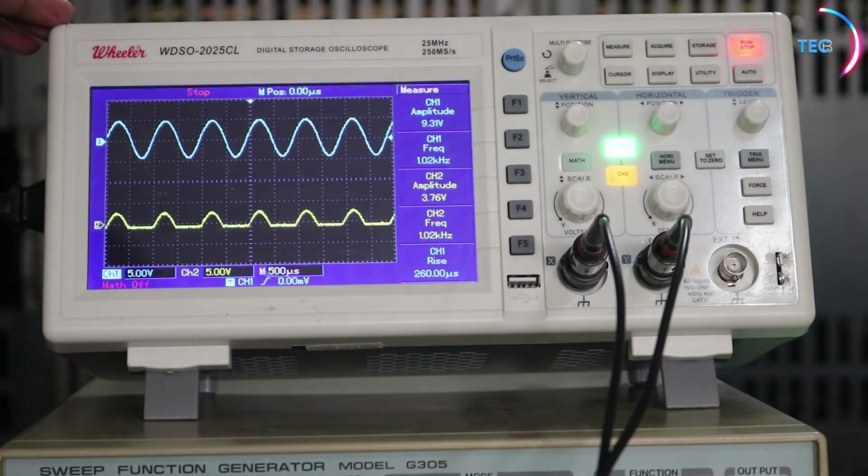This type of half-wave rectifier is the positive half-wave rectifier, wherein the signal cuts off the negative cycle and leaves the positive cycle. If we want to invert the half-wave rectifier, we will just change the orientation of our diode. So we'll just connect the anode of the diode to the resistor.